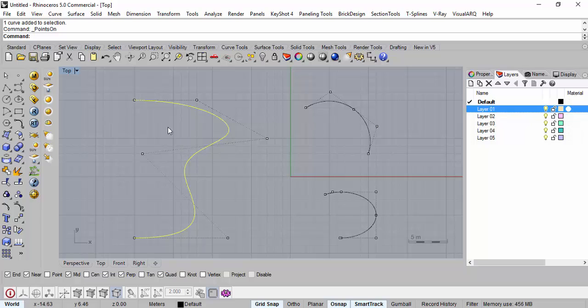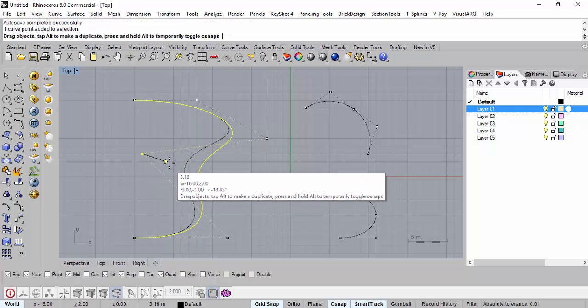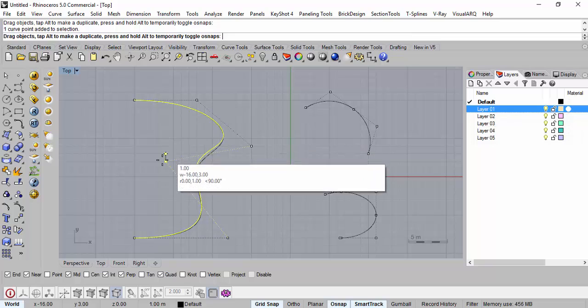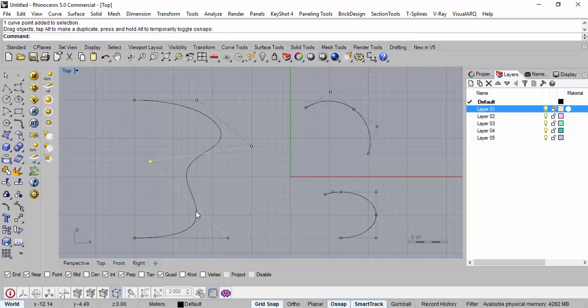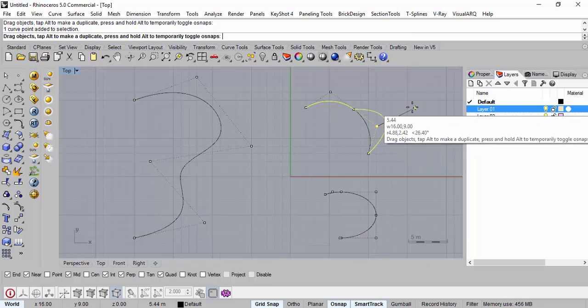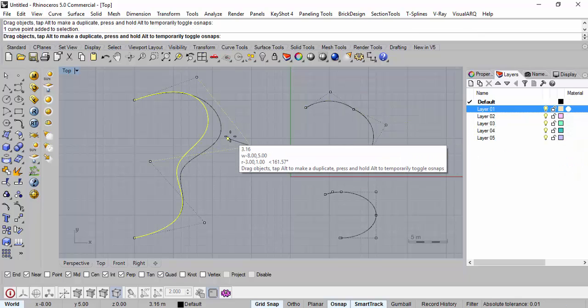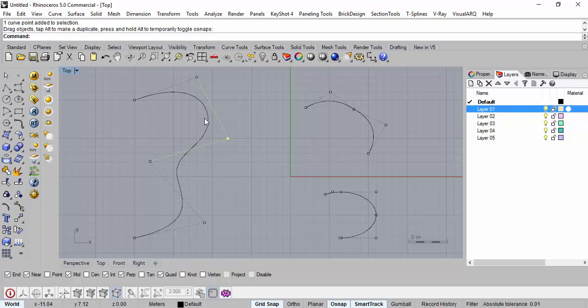Okay, so is this clear about the control points? How Bezier splines or NURBS that we refer to have control points, and how by moving these control points one can control the different variations, smoothness, and other things. If you want to create some sharp kinks, we'll come to that, what a kink is and all that. But essentially this controls the smoothness. Whereas here, see, now you've got a kink here. When we moved a similar point in this, everything else changed, no? It has an effect on the surrounding curve.